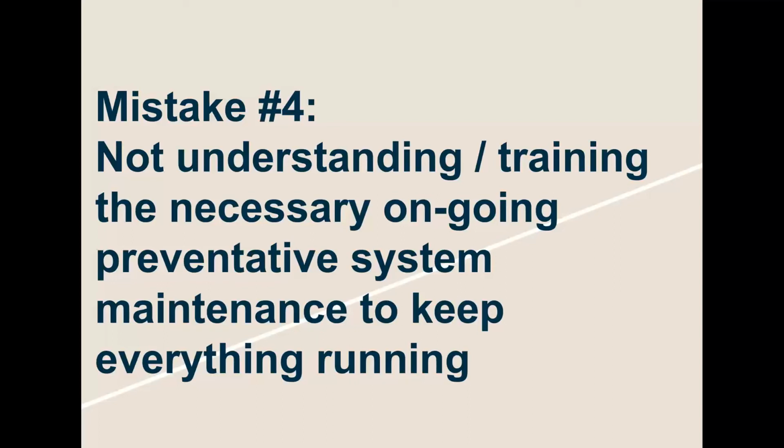As a gas detection company, we have absolutely no recommendation on the calibration of the sensor. If you're getting our smart transmitters, by default, there's a calibration period of 6 months. That's just the default state. That doesn't mean that we recommend calibrating every 6 months. Each and every sensor is going to be different, and the environment's going to be different. You might have the same exact sensor in 2 different environments. One needs to be calibrated every 3 months, and the other doesn't need to be calibrated other than once a year. So it just depends on the environment.